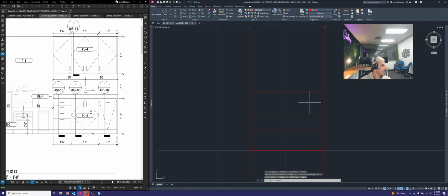All right. Just like we did before, we do want to make sure that we include that reveal since we know that this is touching drywall up at the soffit. So I need to offset this top line down 0.75 to make up for that reveal, which is going to end up shrinking our upper cabinets in the long term, but that's what we'll roll with there.